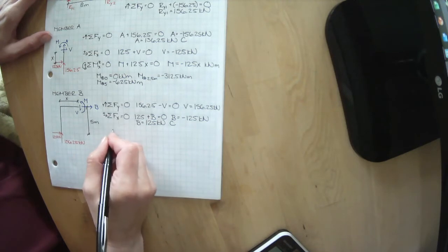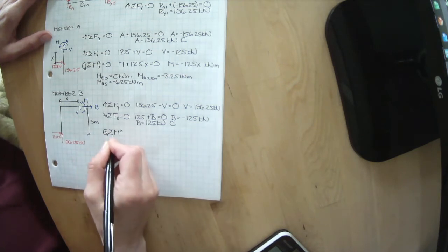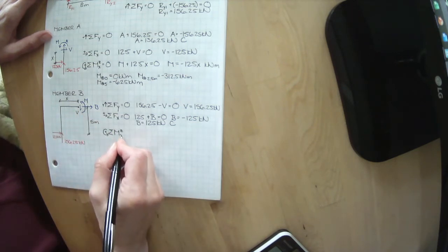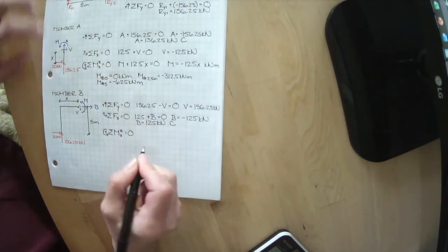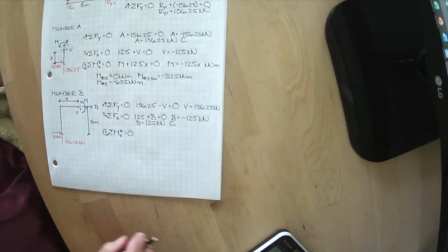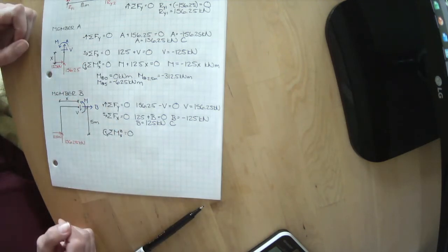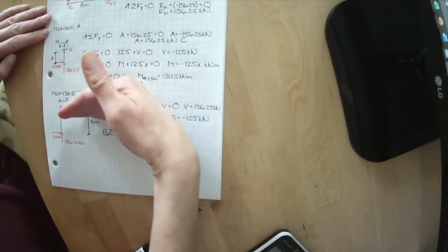We can now sum our moments about the z-axis, where everything in that direction is positive. And let's again pick spot X to spin about. We're going to put our thumbtack right there. Our shear passes through the node, so it's not going to cause it to spin.